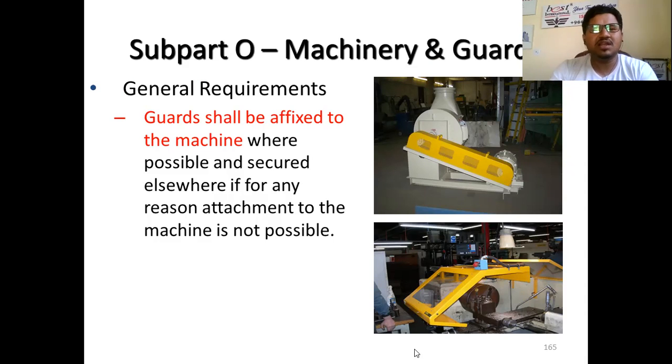So we thought about intentional or unintentional human errors as well, and we sensorized the area, we sensorized even the guards. And there were safety devices or some kind of switches we attached. So immediately, if the machine is running and somebody even touches the guard, the machine will stop. So no chance of incident. Even the area was sensorized. When the machine is running, within those particular areas nobody can enter. If somebody intentionally or unintentionally goes into that area, of course the machine should stop.